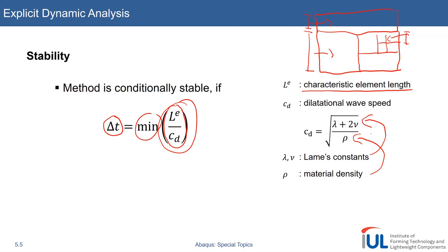So you see, in this method, we only talk about elastic stress waves. That is a key thing to understand. You put an impulse on one node here at the bottom, and what the algorithm will do, because it calculates the accelerations, it will yield such a wave propagation through the body. And you see these also in so-called stress waves. If you look at the motions of the body, you see this wave propagating, but also stress waves.